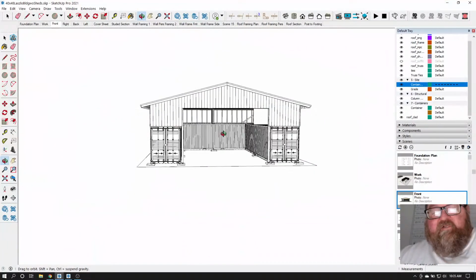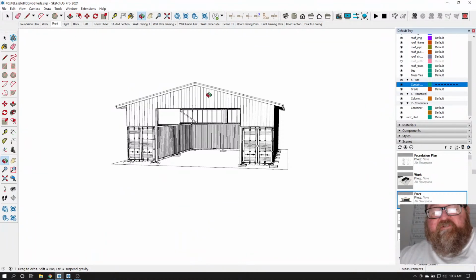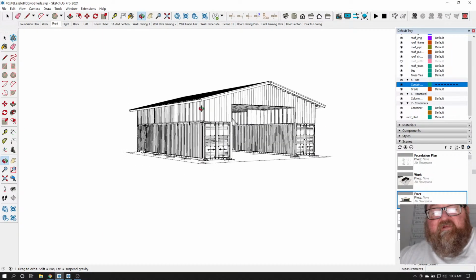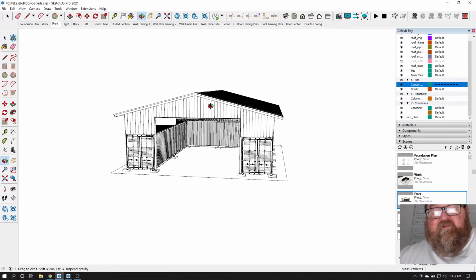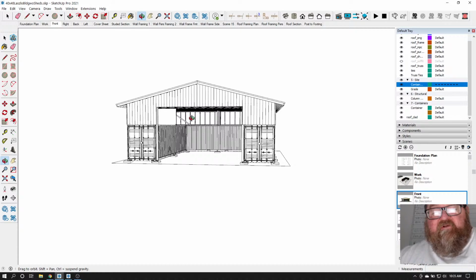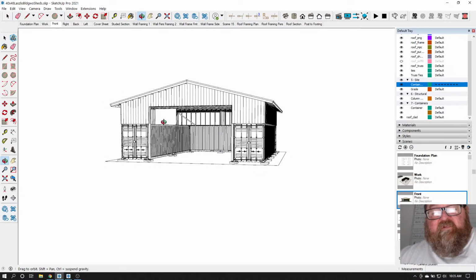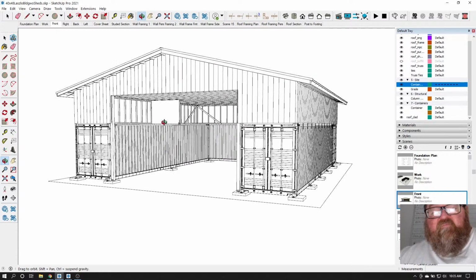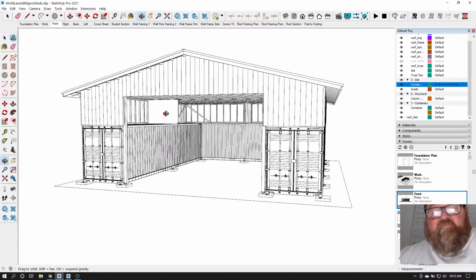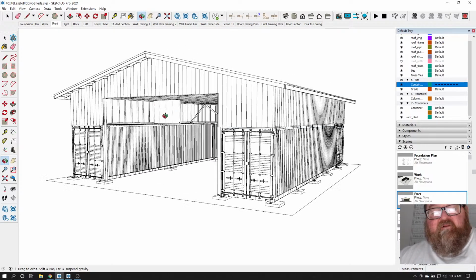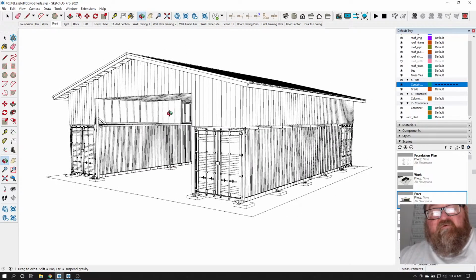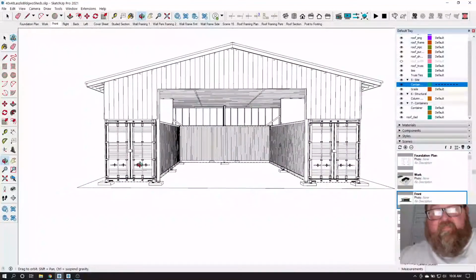Because this building, this top is sort of top heavy, and if you get a big wind, it's going to tend to act on its own. And of course, if you had enough wind, you would have problems with this wall here being unbraced, and that's why we have these shear walls in there.